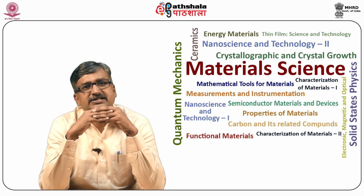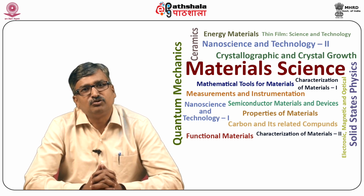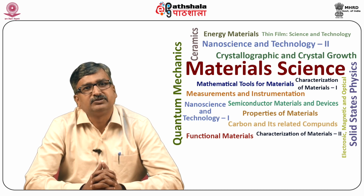With the advent of the transmission electron microscope and sophisticated X-ray diffraction methods, it is now known that fine precipitates are responsible for age hardening in aluminum 4% copper alloy, for example clusters of copper atoms, the Guinier-Preston or GP zone, and the metastable partially coherent theta precipitate, studied by Silcock et al.